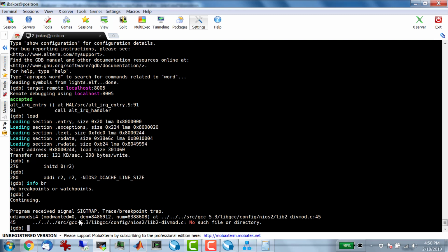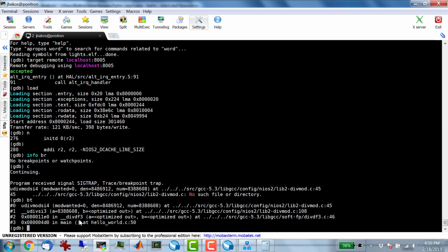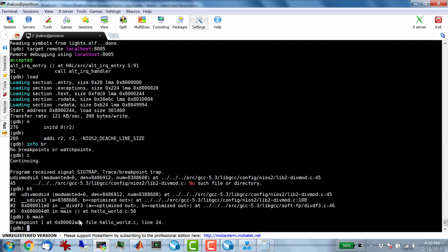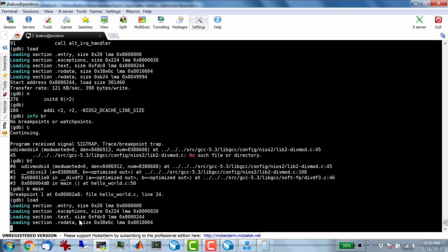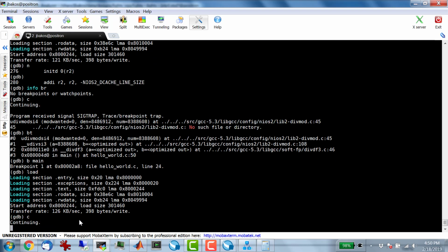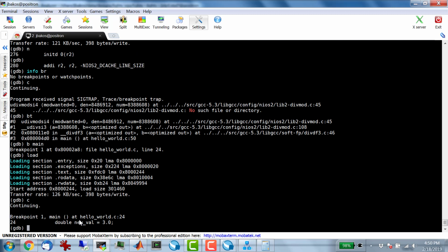Maybe? Maybe not. Oh no, it seems okay. All right, let me break on main. Let me load again. Continue. Okay, no, we're good. So we're at main again. All right, so now the processor is frozen. The program is loaded, but the processor is frozen at the breakpoint.